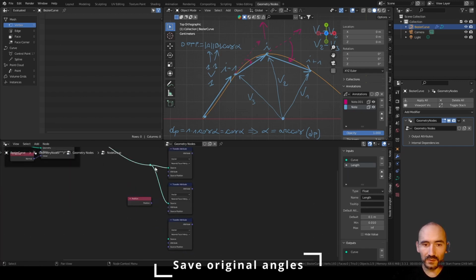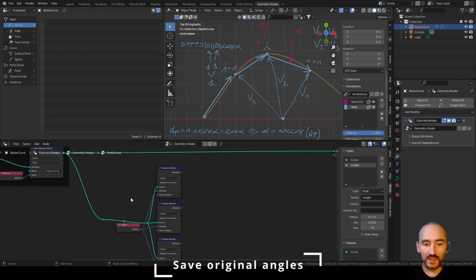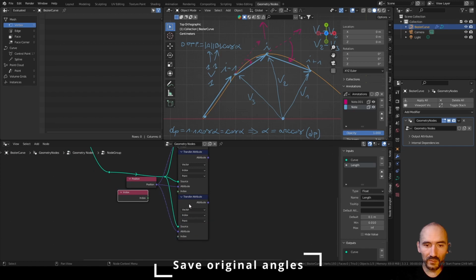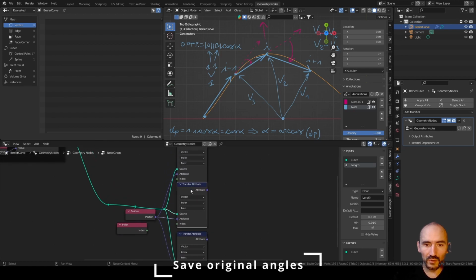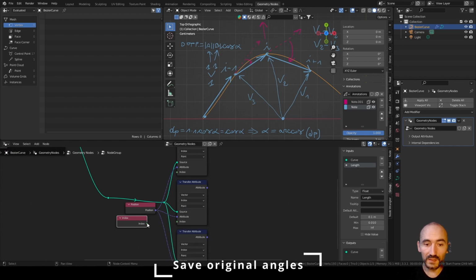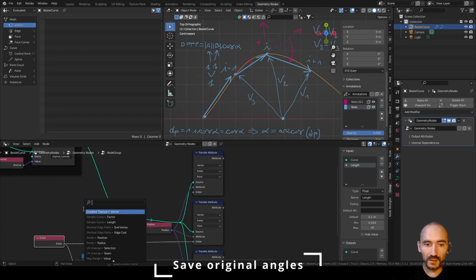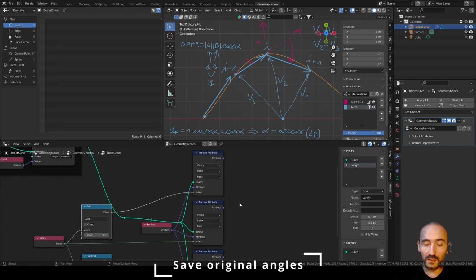For these nodes, I can link this position with Alt and right button to all these 3 nodes. Then I want the index here, and I want to select the index selection here because we have no mesh, so no near to face or interpolation. And I want here the single index. Here I want to subtract 1 to this index and link this output here. And here I want to add 1 and get the index here.